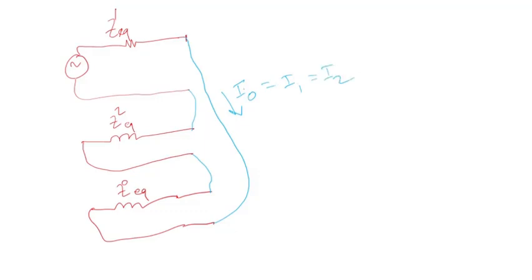So zero sequence, positive sequence, and negative sequence currents. And we will assume this voltage is 1.05 per unit. That's typical when you are dealing with short circuit calculations.